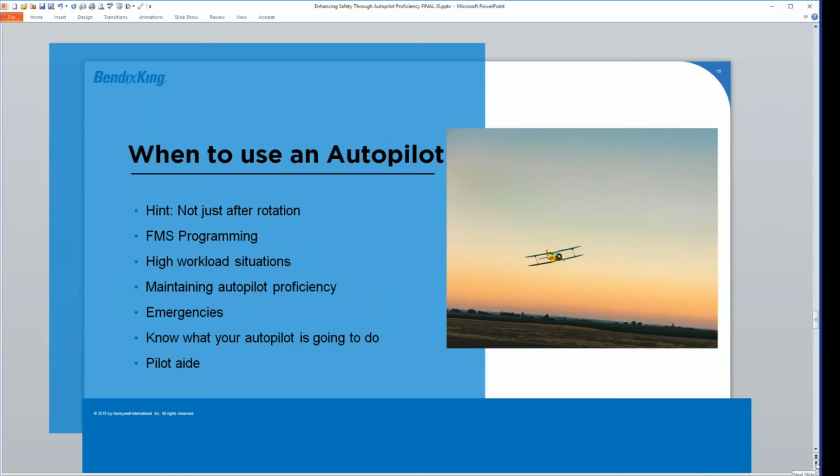Another great thing we get out of these interfaces is sometimes we get an altitude bug as well as other complex mode control of the autopilot. So we can say, all right, we're going to get altitude bug, we're going to get heading bug. In some of these cases, we can do things like altitude select directly from the PFD, as well as when you set the barometer, it pushes that over to the autopilot and all that sort of good stuff. So a lot of what these interfaces do is allow us to interface with the autopilot through our PFD, instead of having to set something on the PFD and then go set it on the autopilot. Like you set your altimeter, it just pushes that across to the autopilot. So a lot of that neat stuff is coming down the road.